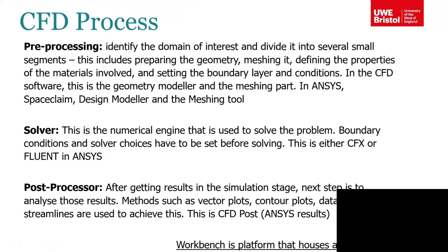So basically CFD can be disintegrated into 3 parts: pre-processing, solver and post-processing. Pre-processing is the commands that you use to identify the domain, do a mesh, and give the boundary conditions.